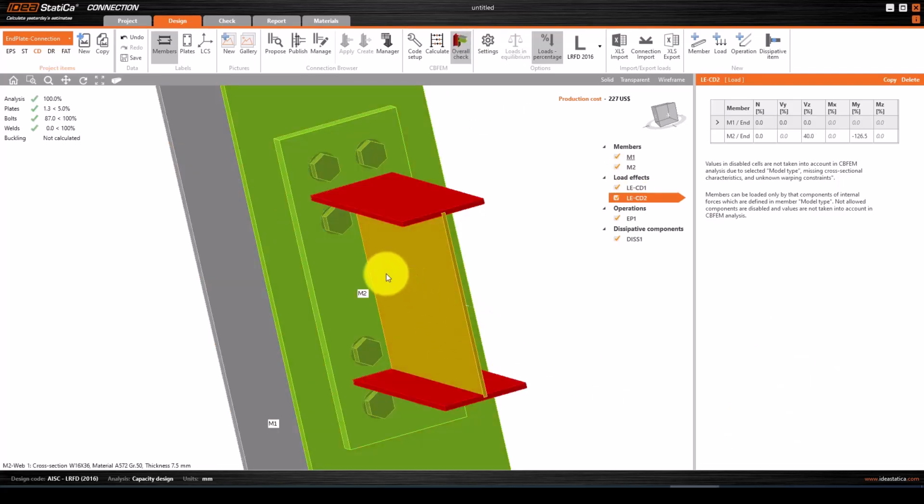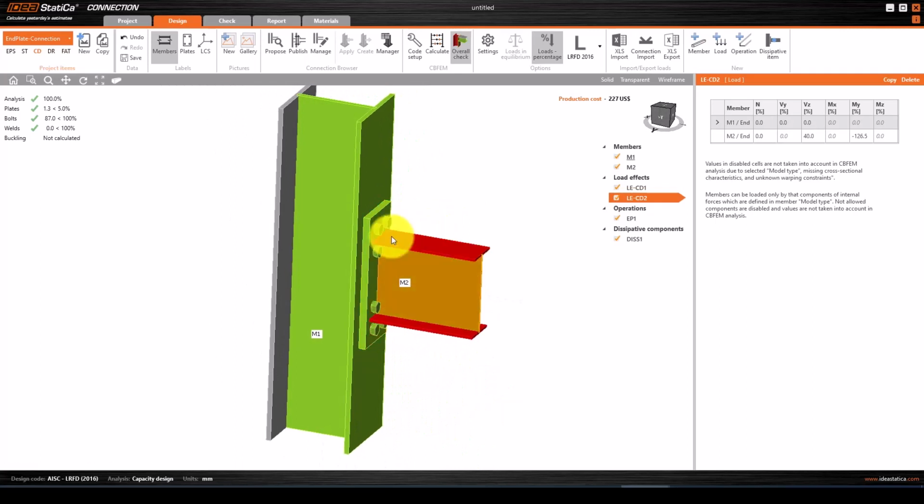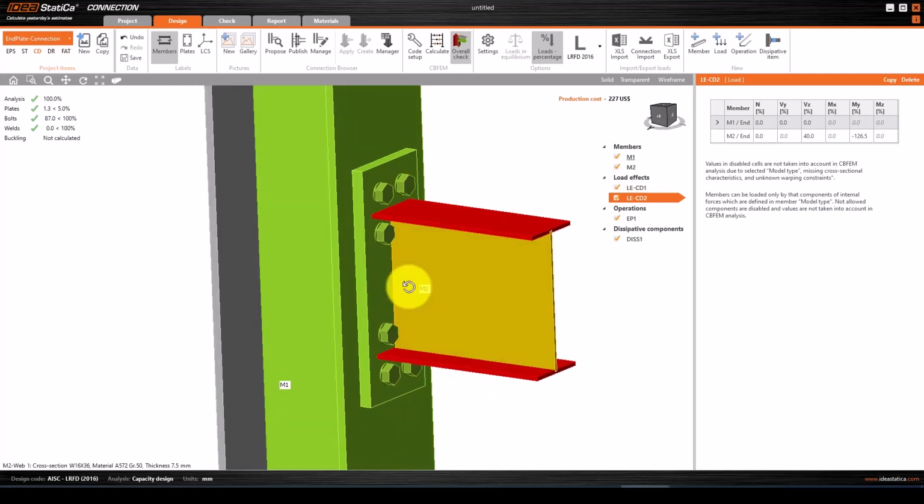Now the result is here, and we can see the beam is not suitable for this loading, so mostly the flange areas fail. But this is not common when you bring an analyzed beam column from another software for design after you designed, because we didn't design the beam column first, we just intend to design the connection. The beam is unfortunately unstable and it fails.